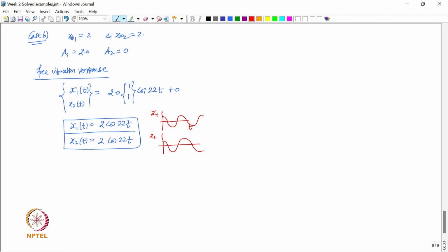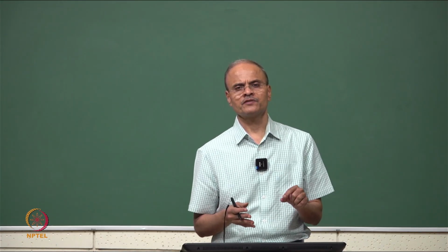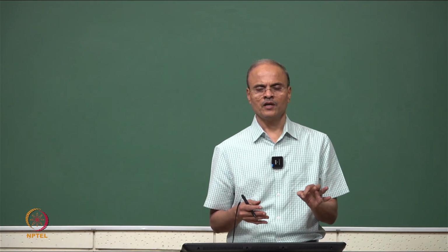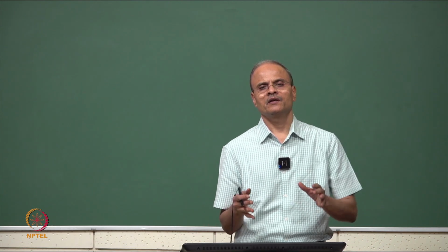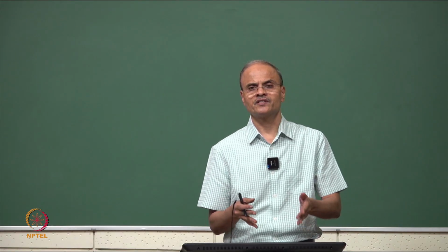And also you see the absolute values of amplitudes, they are like 2 and 2, but if you see the ratio, if you normalize these values, say with x1 amplitude normalized to 1, then the amplitudes would be the same as the first eigenvector, which is [1 1], correct. So, the absolute displacements, their values may be different, but their ratios exactly comply with the corresponding eigenvector, right. So, the first mode shape completely determines the displacement shape of the vibration profile or the pattern of the whole system, because in this case it is vibrating purely in the first mode.